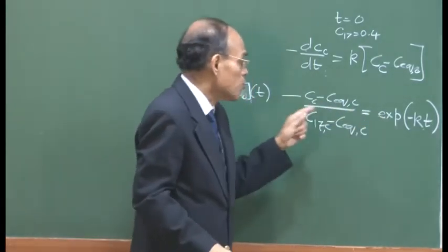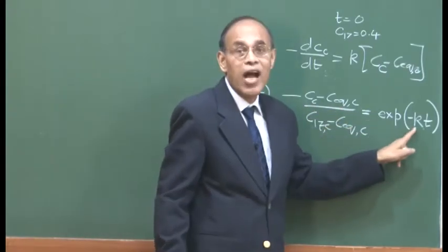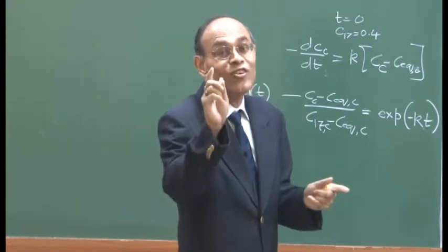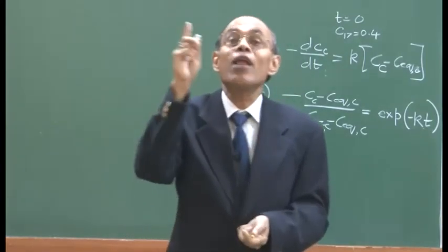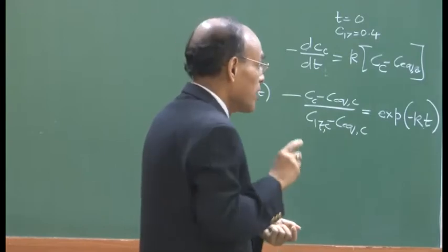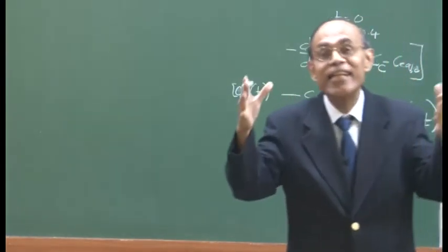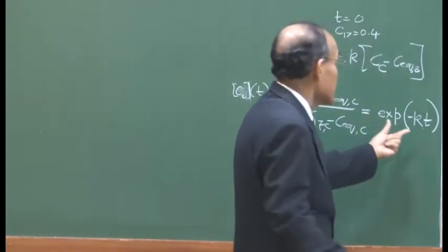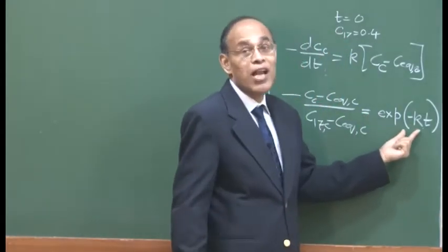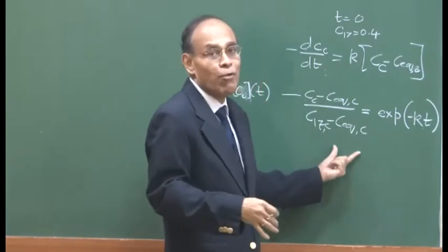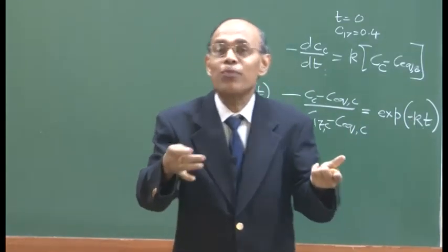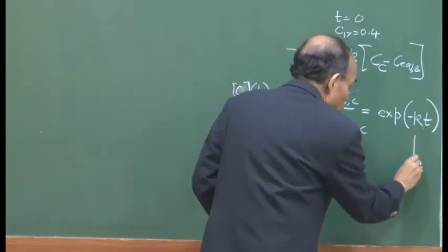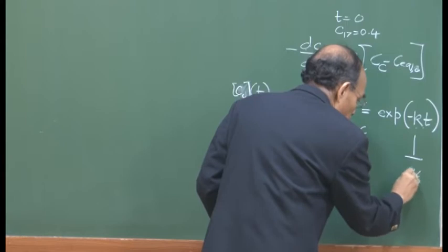And this allows you, so therefore, if you know the rate constant, how will you know the rate constant? There is no shortcut. Rate constant is an empirical parameter, and that will have to be determined. And therefore, when you install an LD converter in your plant, in order to have this kinetic equation exactly established, you have to determine the rate constant, and then only you can have this kind of a model, then you will have a chance to predict the endpoint correctly. So unless and until the rate constant, which has a dimension of 1 by second, that is the dimension,